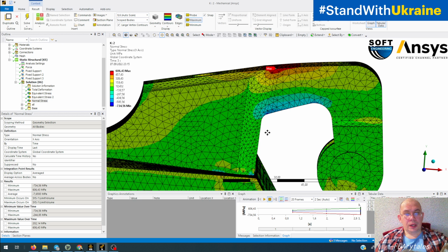So that's why most programs use non-linear or quadratic or parabolic. It's the same type of elements. Non-linear tetra, quadratic tetra, parabolic tetra, tetra with mid-side nodes, it's the same term, for solving physical tasks for computational mechanics.